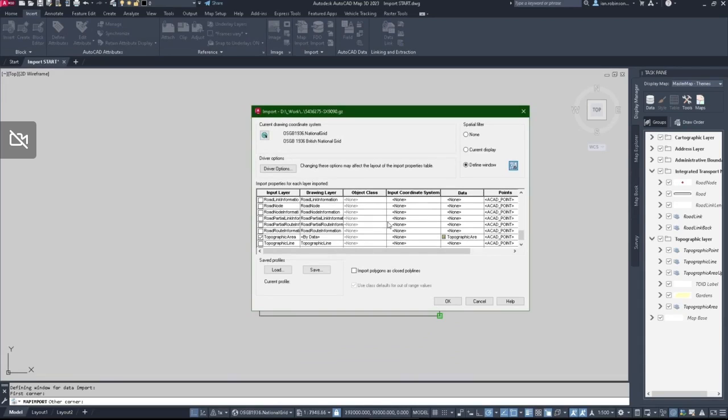Now, for the task I'm about to do, I need to do some data processing to allow me to attach building height information into here, and then I'm going to extrude, make the lines into solids and make them the height of the building data. Now, in order to do that, I need to make them lines, not polygons. So when it brings a building in, it won't be an M polygon, it will be a polyline that's closed. That's important for this particular task, but not necessarily important for all of your input tasks in here.